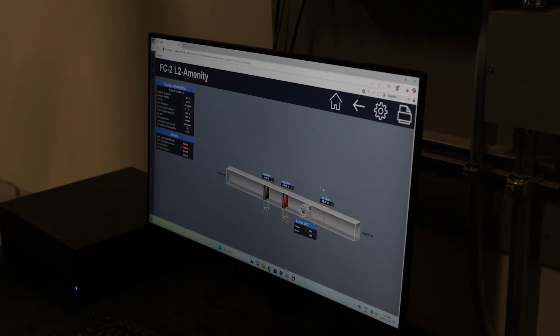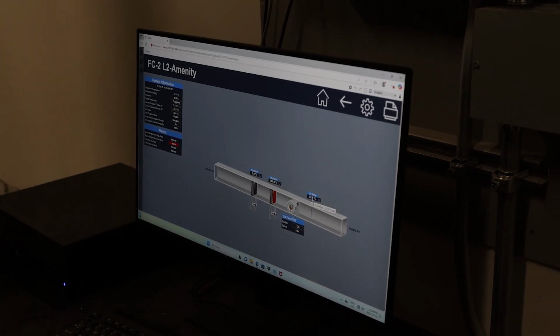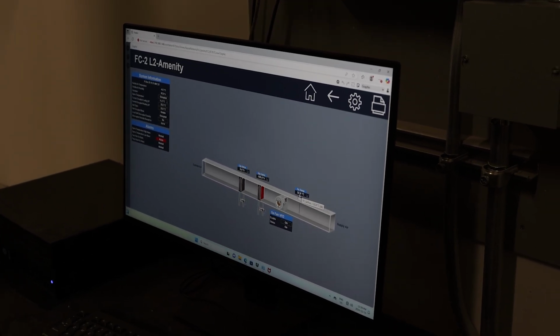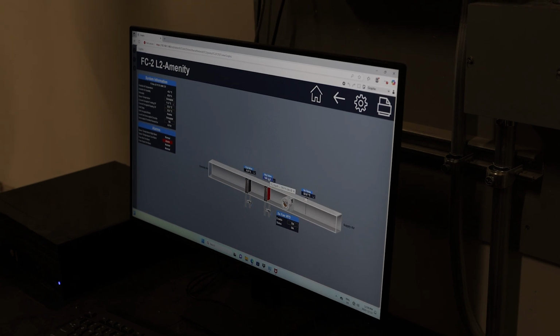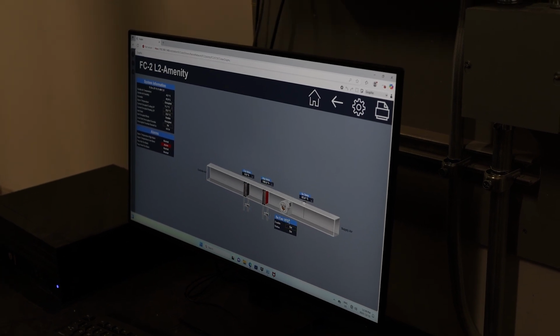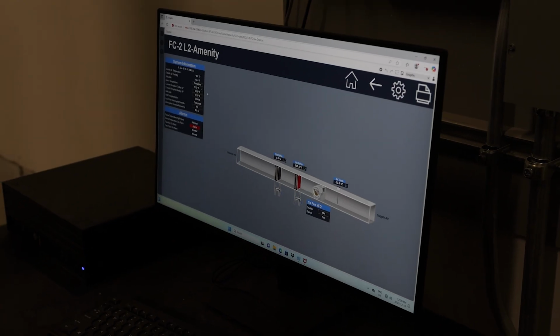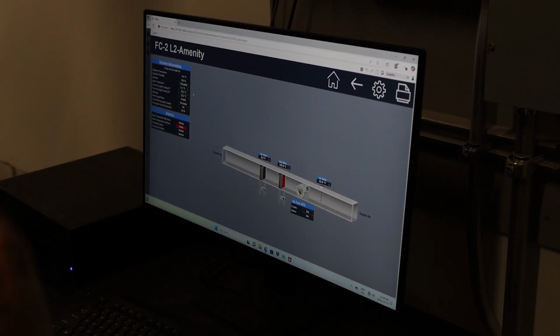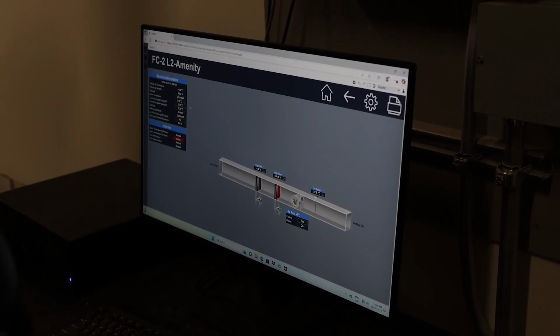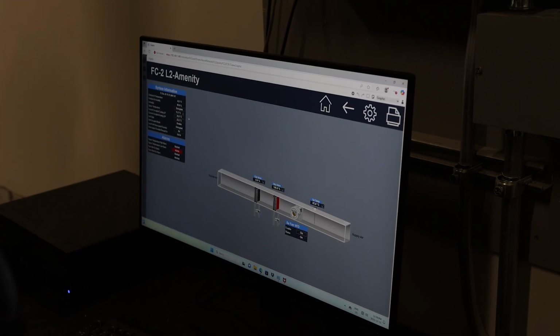But I know the discharge temperature is 33 degrees C, so its heating valve is open, the fan is running, and it does supply heat to the room. It's just because the room has an outside door. That door is open and closed the whole time. That's why that room is just so cold right now.